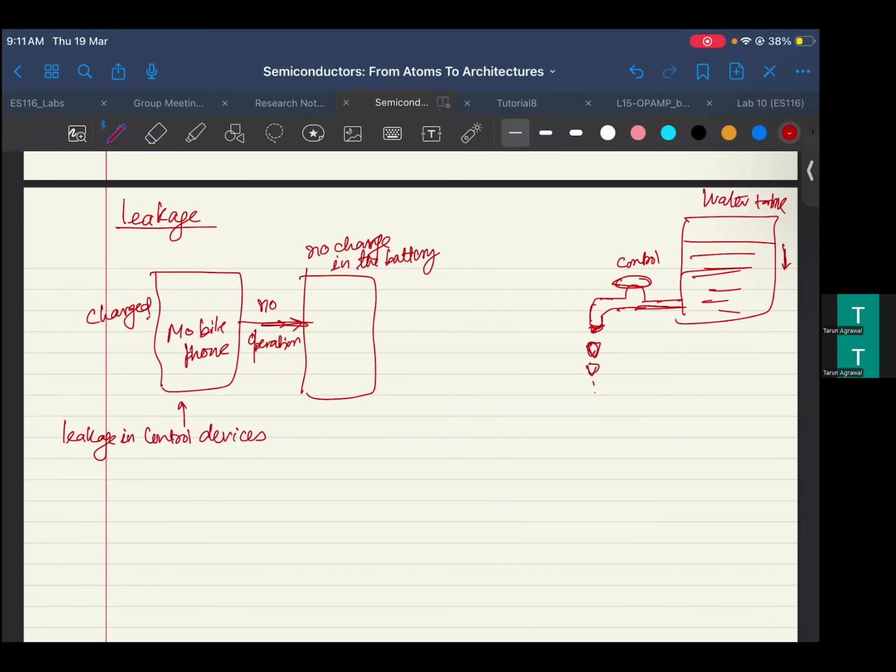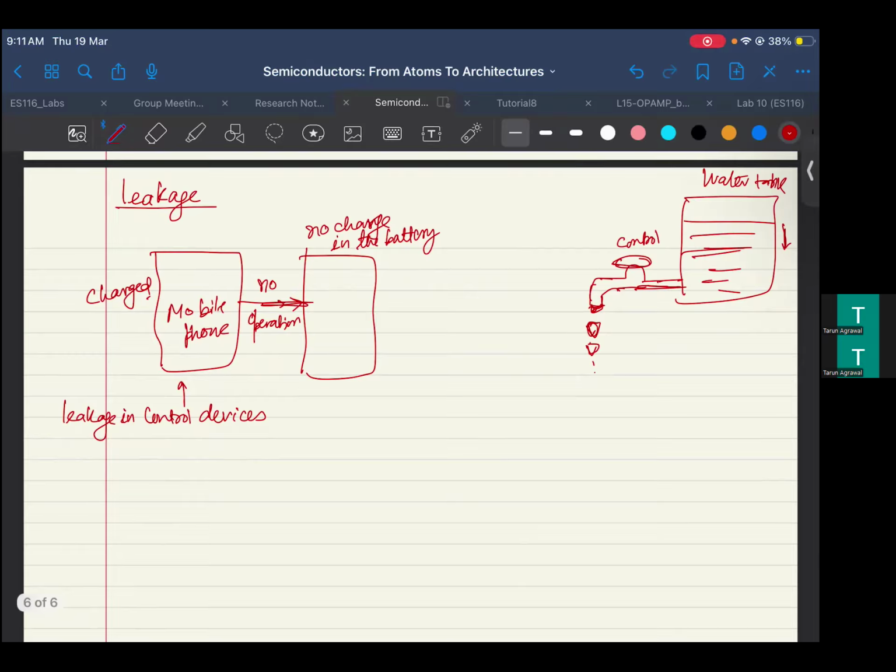Before this, if you have not watched the video on DRAM, where we talked about the building block inside the DRAM, maybe look at it so that you can better get the context of what we are talking about. This is the circuit which we said is the workhorse in a DRAM, where you have a transistor which tells you which bit to control, because you have so many bits. There's a control signal coming here, which we know as the word line. There's also a signal here which is basically what do I want to do? Am I reading, am I writing?